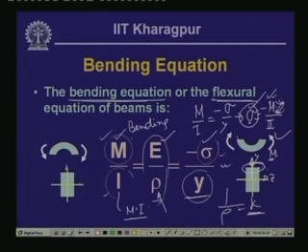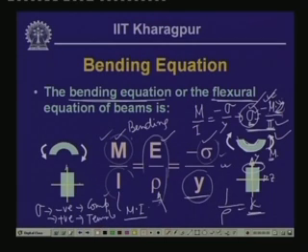So, at the upward point, at the extreme point, we have a stress which is negative, and as you can see, physically, because of this kind of bending, the top fiber undergoes compression. So, negative means compressive stress. Taking M as positive and y as negative on the bottom side, the stress becomes positive, which corresponds to the stress at the bottom fiber. So, when we get sigma as negative, we call that compressive stress, and when we get sigma as positive, we call that tensile stress. This can be verified for this configuration, where the moment here is negative, M is negative, because it is in the opposite direction to what we have assumed as positive.